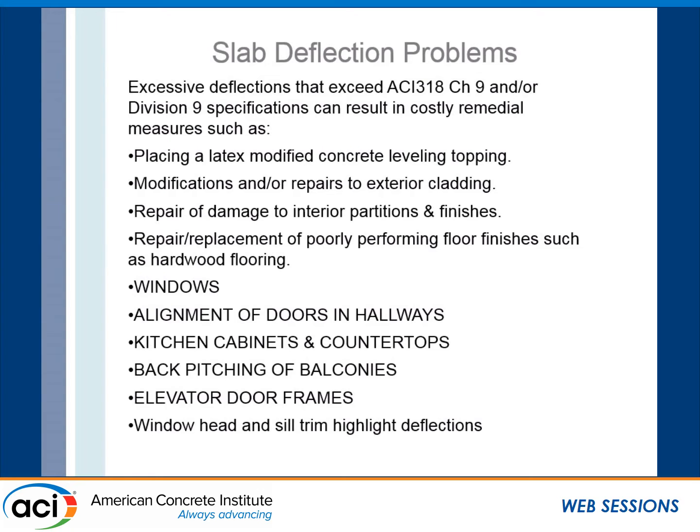What I mean by that is you have a particular window trim, and it's true and plumb, and the slab edge may not line up with that. Or you might have a trim piece that is level, and you might have deflection, which again gives you two lines that should be parallel, and your eye is drawn to that.